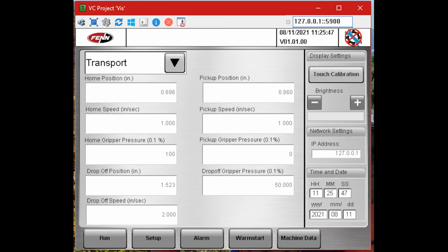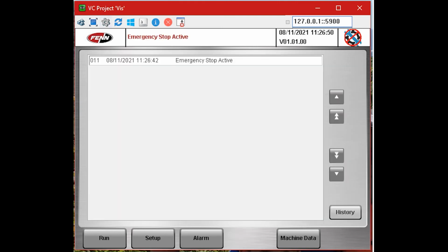Now that we have covered the behind-the-scenes controls of the feeder, it is time to describe the 4th main screen titled the alarm screen. The alarm screen displays active alarms that will disable the swager feeder from running. The NF automated feeder contains 10 alarms, with each one of them needed to be resolved and reset before a production run can occur. In order to reset any active alarms, the alarm reset button, located either on the operator control station and/or the run screen, must be used. Note, the motor will need to be re-referenced after resetting any alarm.